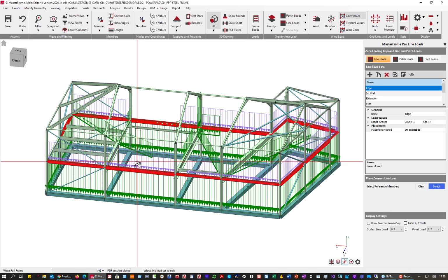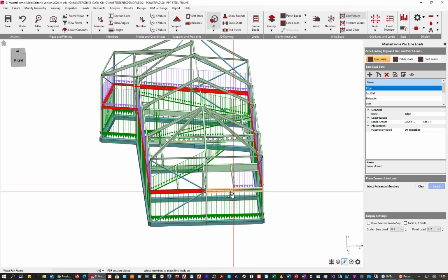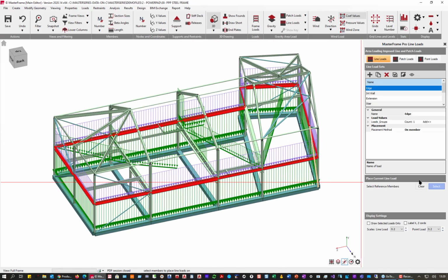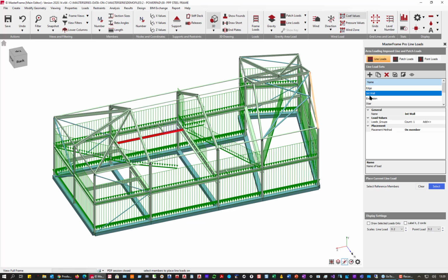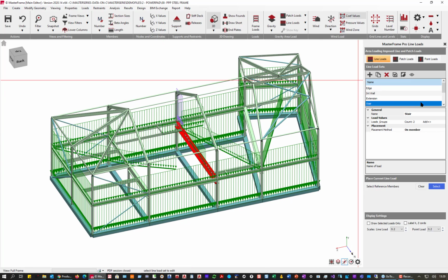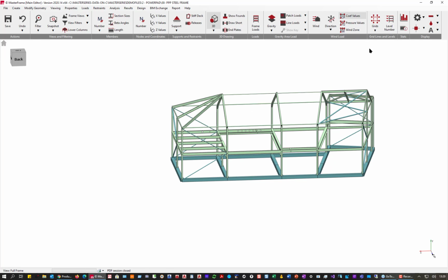We're dealing with this set of loads, and we can just say select, and we've applied it to those members because those were on member loads. And likewise, we probably should have something around the back as well. So that was on member. You can see we can have off member loading as well. So if I go internal walls, you'll see there's an internal wall extension. We have all the different stair loads and all the different loads applied to that structure. Very straightforward, very powerful, very flexible. So that's your dead and live loading applied. Patch loads, point loads as well.